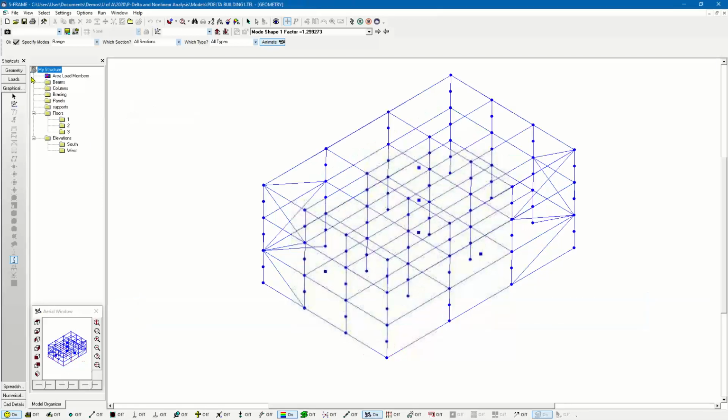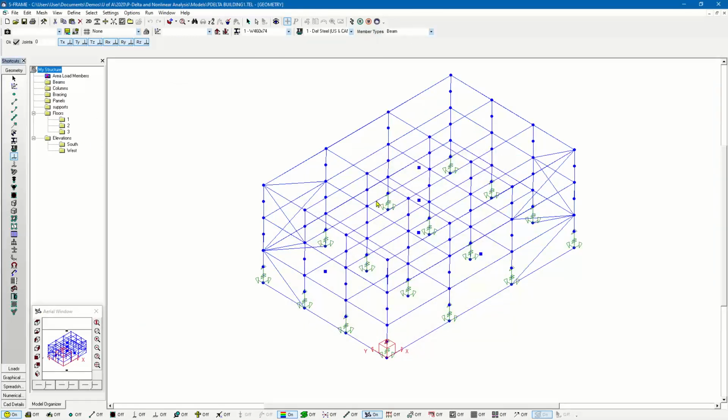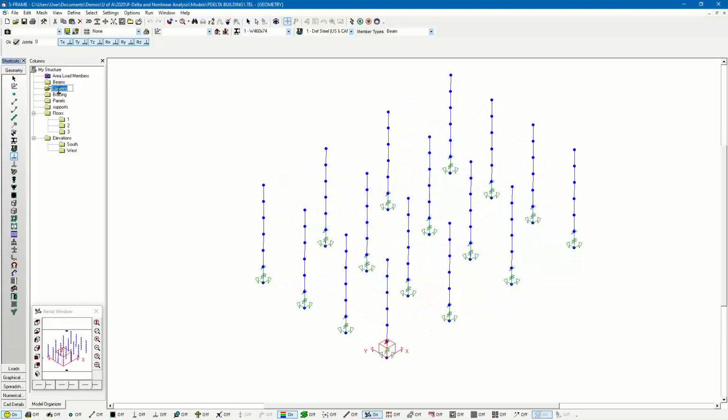So now I can go into the geometry window and say, well, I know these interior columns were the ones that were a problem. Maybe I'll just select my column folder here. I just want to see, is there anything different about those columns than the other ones? Maybe they just have more loads. I mean, they are in the interior. But let's just check, first of all. I go to the member release tool to see if there are maybe different release member end conditions. Also materials.